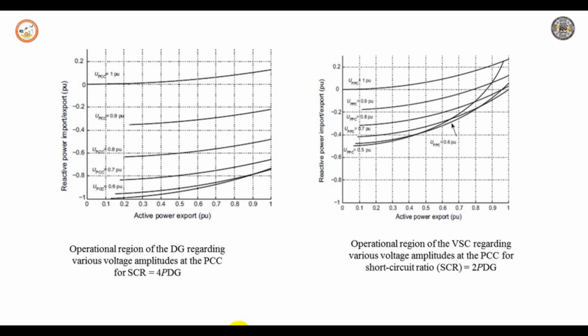This may trip the overcurrent protection of the converter and electrically disconnect the DG from the grid. However, if the voltage regulator is adaptive, in the sense that the reference voltage value may change according to the DG operating point, the system may survive through boosting the voltage to a level lower than 1 per unit.